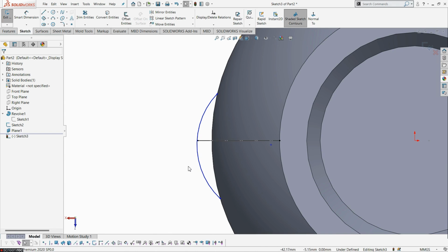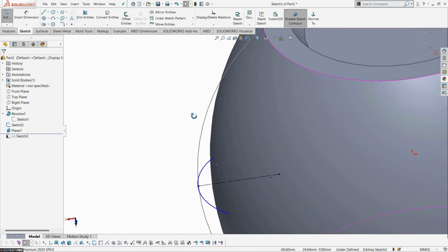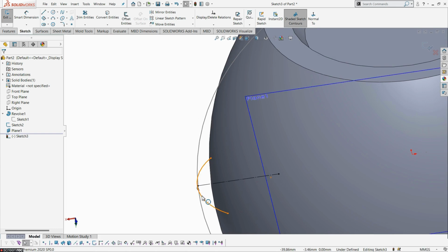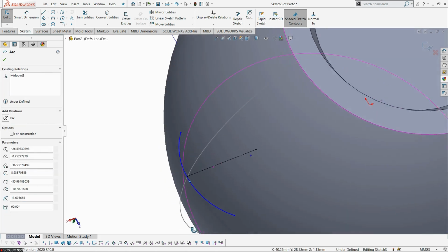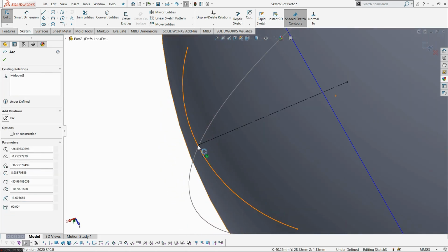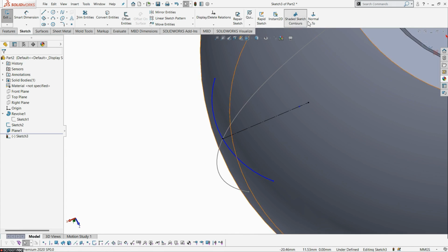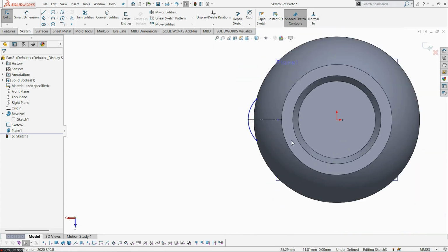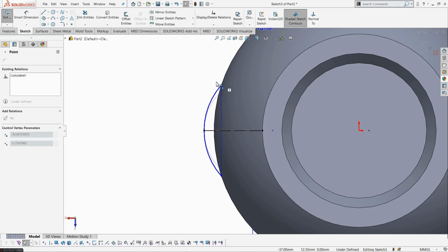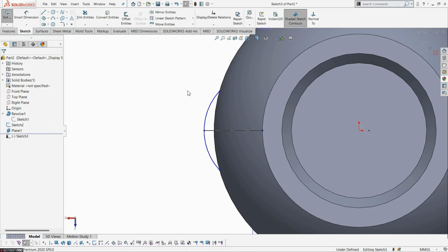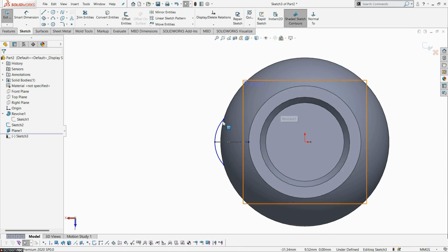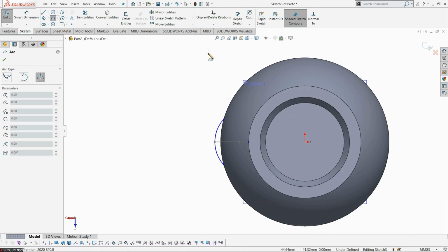Now fix the sketch at the center point area. So selecting this arc center point now and the end of its construction lines. Okay, now the center point of this arc profile is fixed at the center of these construction lines. Next we need to fix with smart dimensions. That's why I am going to draw another arc profile, because in this top view we have only one dimension recommended to fix this area, that is an angular dimension. That's why I am drawing another arc profile.